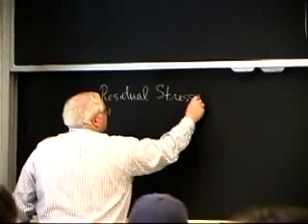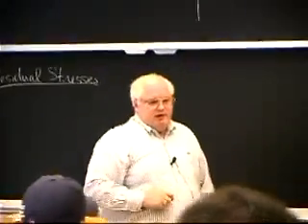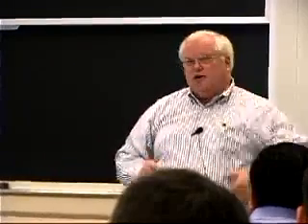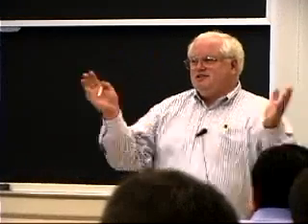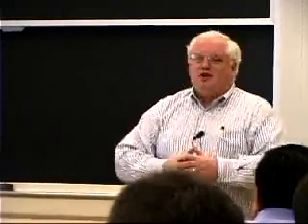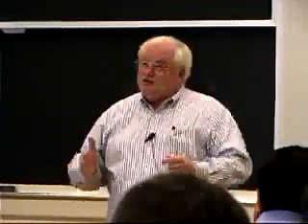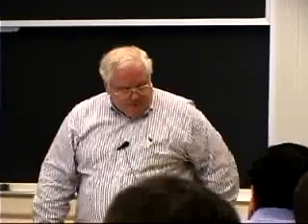All this stuff I said about stress concentrations and stress intensities, if you go and do all the analysis and try to put the numbers on it and you still can't explain it, you invoke residual stresses. Okay, that's the final out always. Oh, there must have been residual stresses present, and that's a great one because it's very hard to quantify what the residual stresses are. However, they exist.